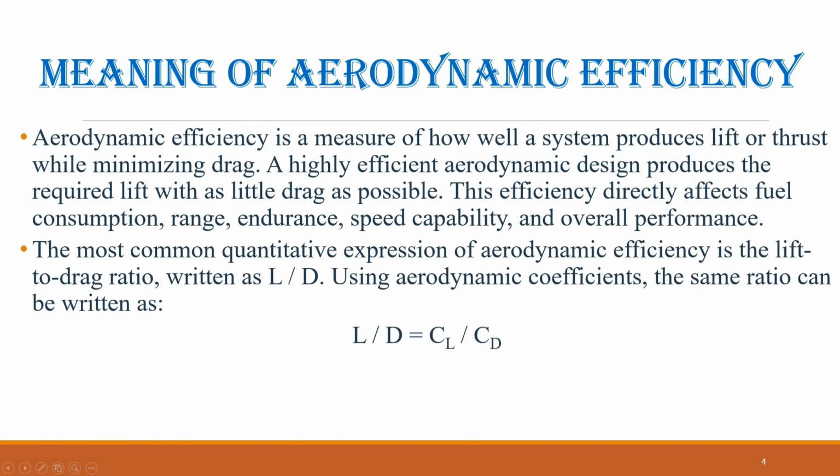Meaning of aerodynamic efficiency. Aerodynamic efficiency is a measure of how well a system produces lift or thrust while minimizing drag. A highly efficient aerodynamic design produces the required lift with as little drag as possible. This efficiency directly affects fuel consumption, range, endurance, speed capability, and overall performance.